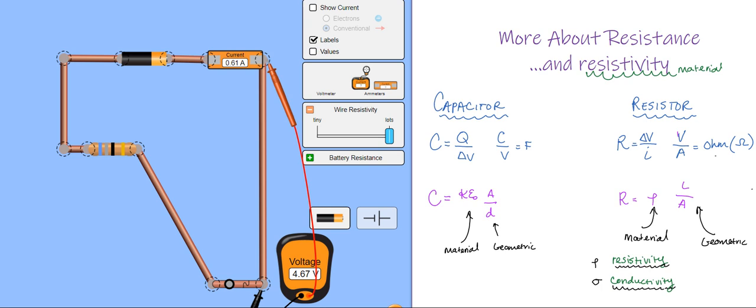Georg Ohm is who this law is attributed to, and it's oftentimes misinterpreted a little bit, and we're going to look at that in some greater detail. And the reason for that is Ohm's law relates current and voltage to one another when resistance of the material, or the resistance of the resistor, is independent of the current and the voltage.